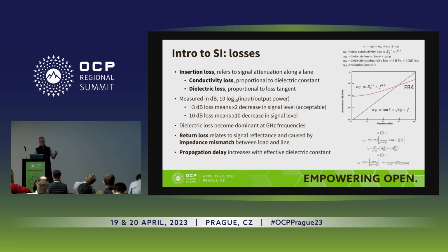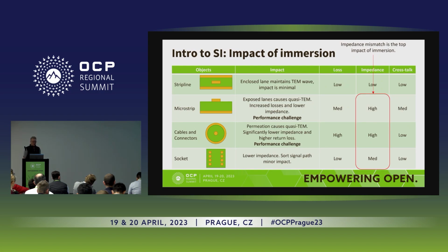Not to say that the dielectric choice isn't important below gigahertz frequencies. What we're really saying here is that the tan delta losses, that second property, becomes a critical consideration. So we look at this, and we do tests, and we do calculations for those 4 structures that we talked about. And what we find is that the major impact on performance is really around the change to that Z value, that impedance.